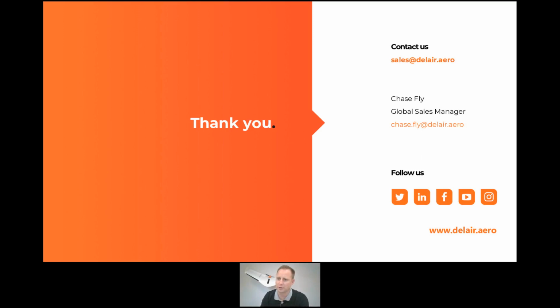A new question, will you use the PPK and GCPs as before? So I think the question is, will you need to use PPK and GCPs as before? That's of course up to you. These features actually have no impact on your workflow in terms of accuracy and precision. So PPK, absolutely. In fact, 98% of UX11s are purchased with PPK. I think most people looking for this kind of a solution do want that high accuracy. A lot of people still use GCPs, and that's totally fine. It really depends on your project requirements.